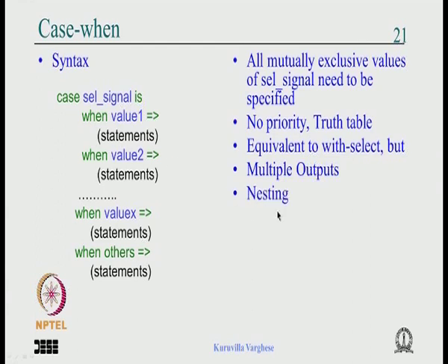And you can do the nesting, you can nest a case within the case, that means you could say case select signal is when value 1, under that maybe you might say case some other signal is, then you could make nesting, or you could say when value 1 if some condition.